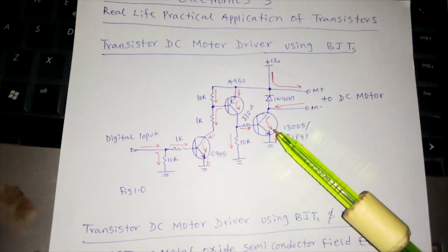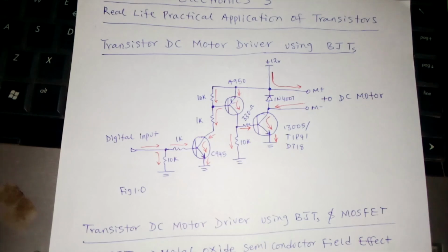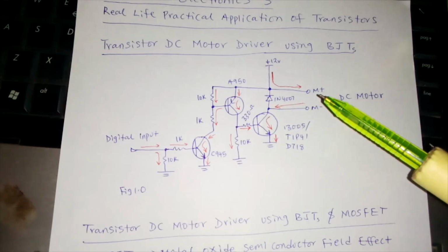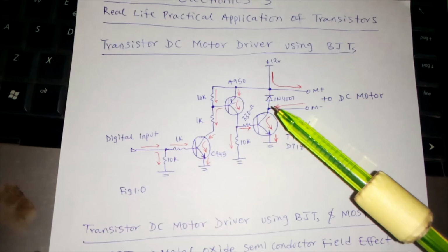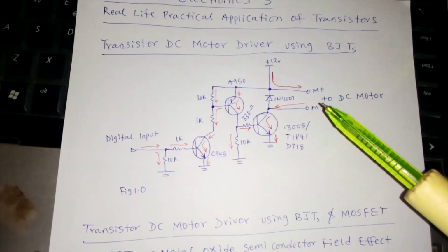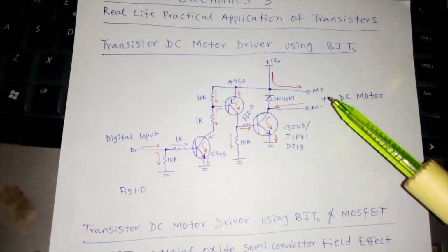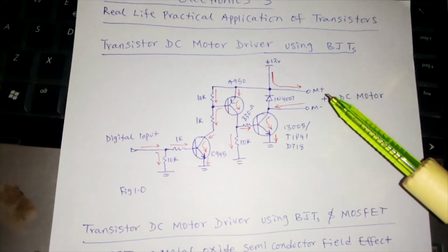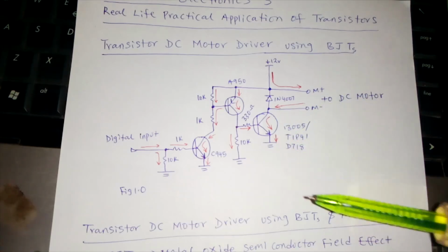It can destroy this transistor, which I have practically confirmed. So whenever you are driving anything that has a coil, make sure you put a blocking diode there. Here I use a 1N4007 to block the back EMF, so that the voltage produced by the coil does not destroy this transistor.